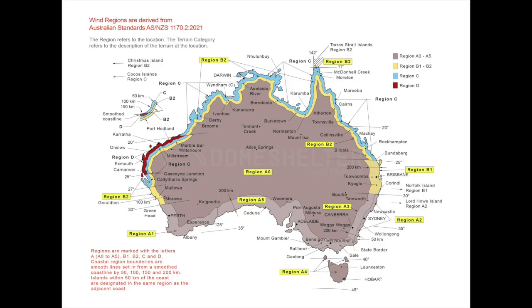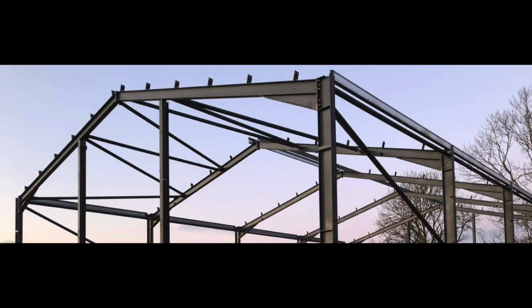With transferring our Revit portal frame structure into SpaceGas, it helped further improve and test the structural design to ensure it was compliant with the AS 4100 standards, as the structure is subjected to loads under conditions found in the A2 wind region. Through extensive analysis, we were able to extract the dead and live loads, the internal and external wind loads, and the internal longitudinal loads from the data exported from the 2D model into an Excel.